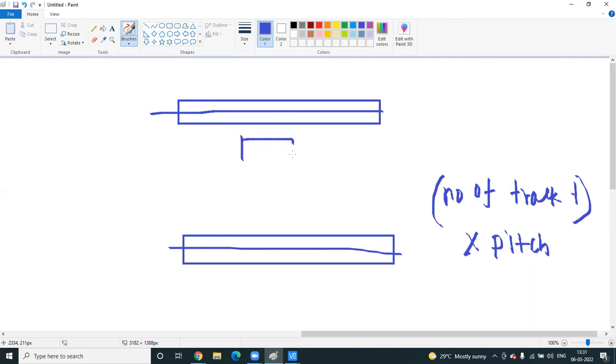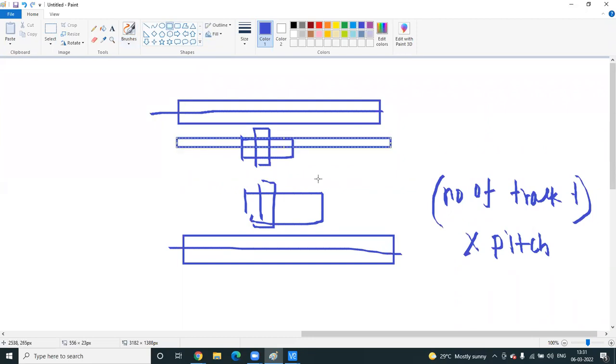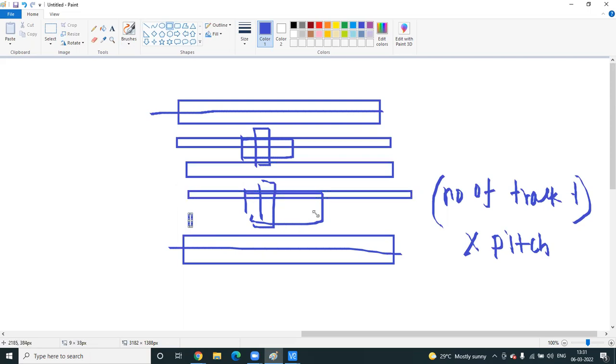Okay, so let's assume your devices, one is PMOS, one is NMOS. This is your tap. Track just means a metal drawing path. You draw these, and they are called tracks. Here you will do the metal track, meaning you will draw metal only above that layer on the track. Track is just a virtual layer.